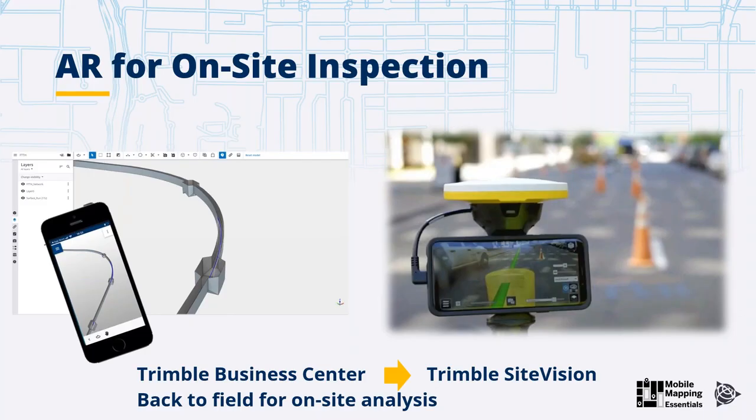Once you have defined the geometry, you can decide the elements you want to include in your utility network, for example, manholes, the type of manholes, at which height with respect to the ground, with respect to the surface, what the template of the trench you would like to build is, where the utility line will be, and what the clearances are between the pipe and the sides of your trench.